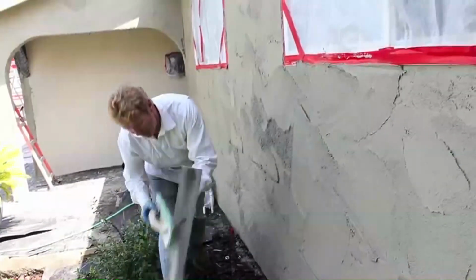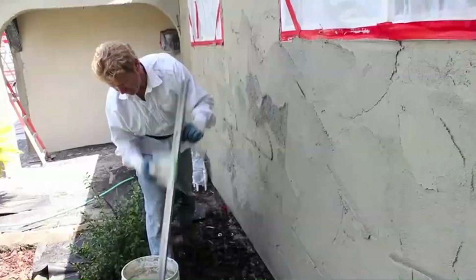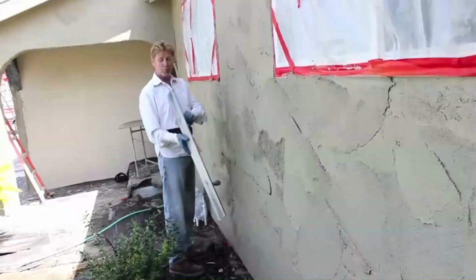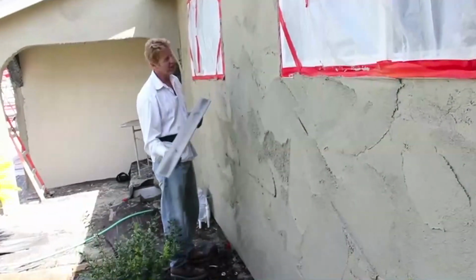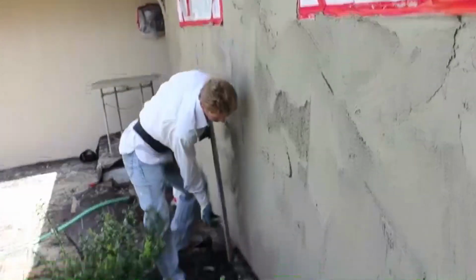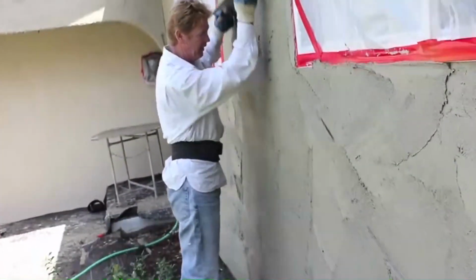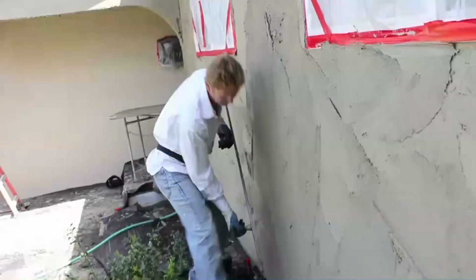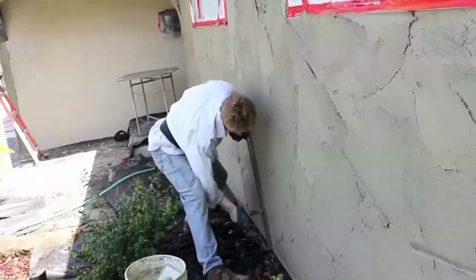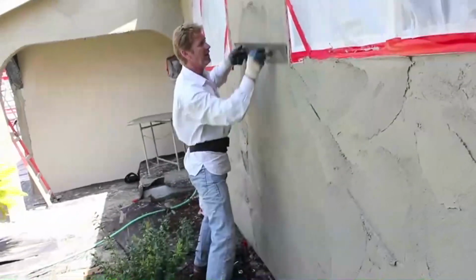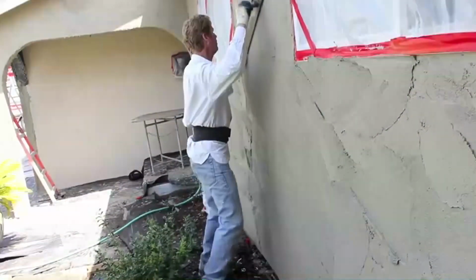Here's what we do over here. Now these are more popular all over the US and Mexico, and they've got some good plasterers there. You take this Darby, you can call it a straight edge or rod, you grab this guy right here. You come up and feather into it. You just put the excess where you need it. Take your leg, put your elbow back here, come up. This is the second coat, making it true and plumb.